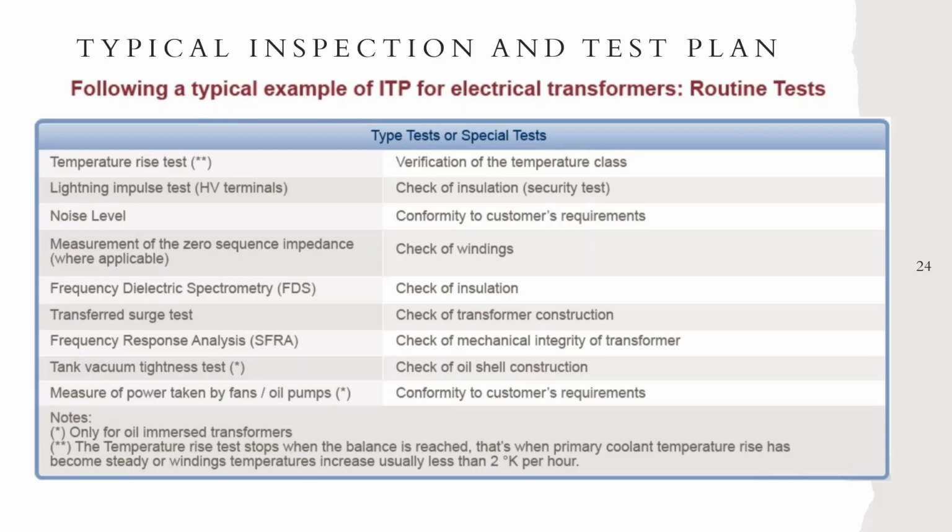Then another: type tests and special tests. We have special tests for our transformer: temperature rise test, lightning impulse test, noise level, measurement of zero sequence impedance, power frequency dielectric, transferred surge test, frequency response analysis, tank vacuum tightness, measurement of power taken by fans, etc.